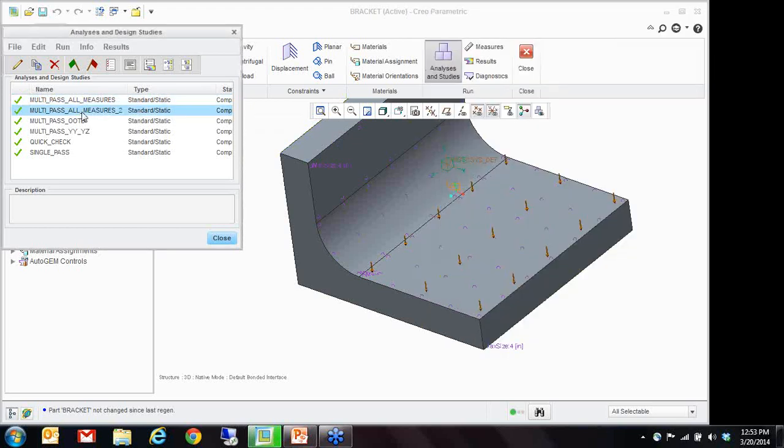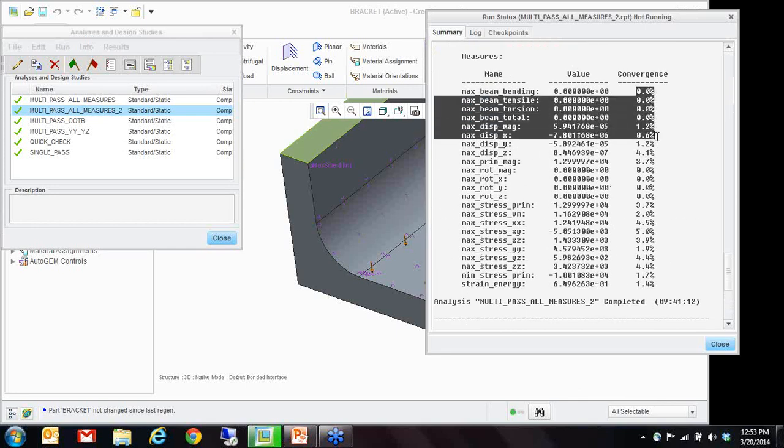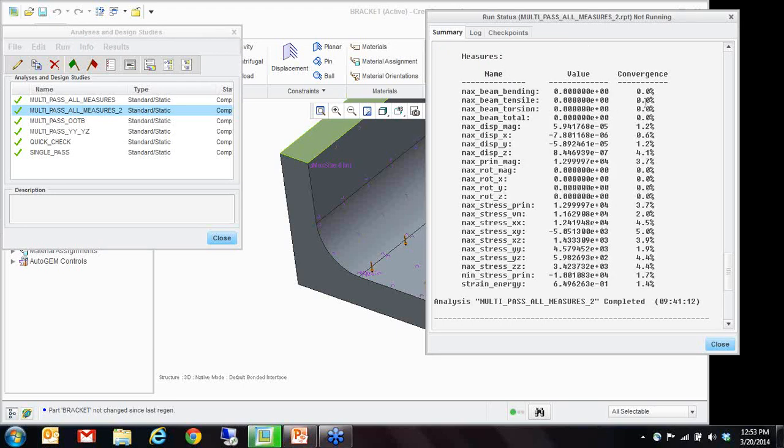Okay, so I run another analysis which will force them in, and here you can see all the percentages right here are converged. So you keep force converging. Once these are converged is when I really care about these. If these don't converge, don't even bother looking over here.